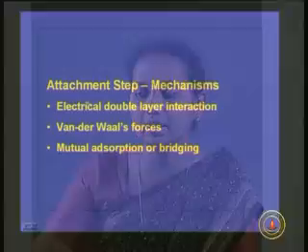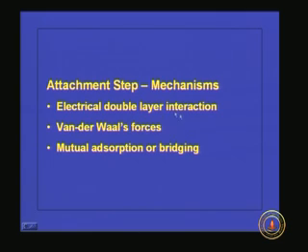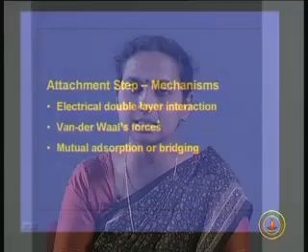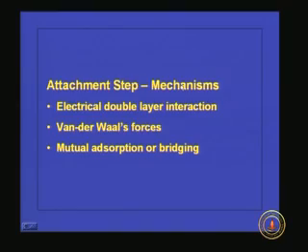So, what is happening? If you consider this electrical double layer interaction, how does it take place in the filter? There is the filter media and your particulate matter is coming. Where is the double layer formed? The filter media, most of the time, is sand. So, naturally that also will have some ions attached to it, and the liquid is moving through that filter media. So, what will happen? The electrical double layer will be shearing off.